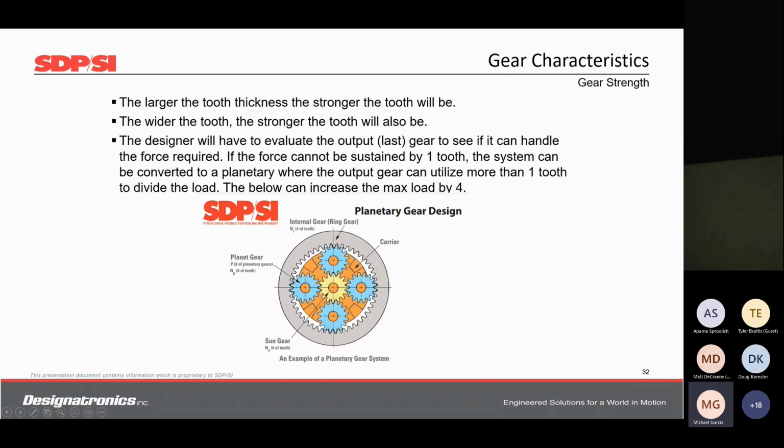One of the drawbacks here is that the gear carrier must be highly accurate. And the shafts in the gear carrier must be true to the gear, total composite error. So if you have an AGMA 10, that gear carrier pin has to have the same concentricity as the spur gear requires for total composite error. Otherwise, you'll have binding.